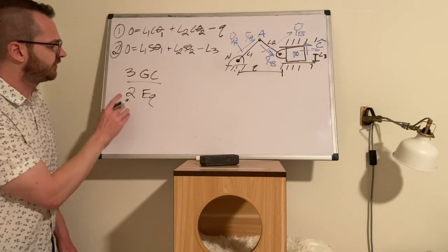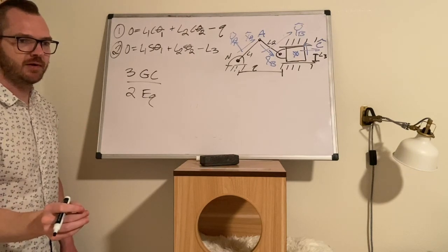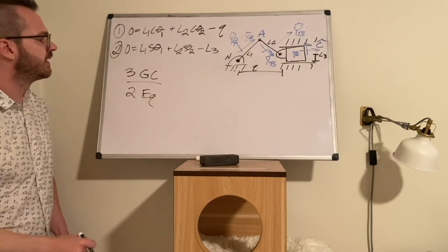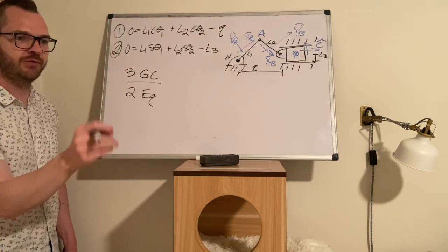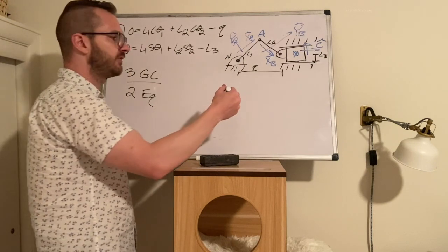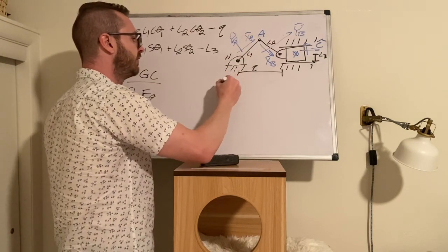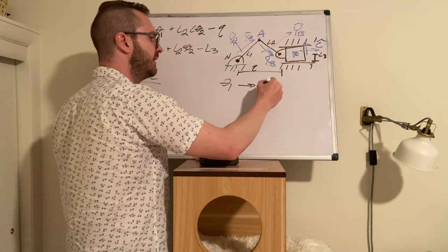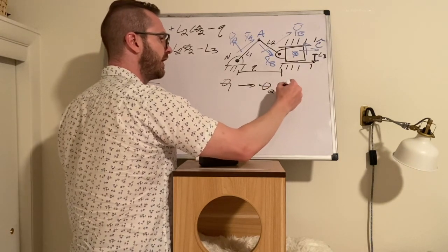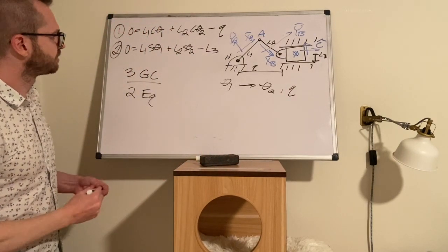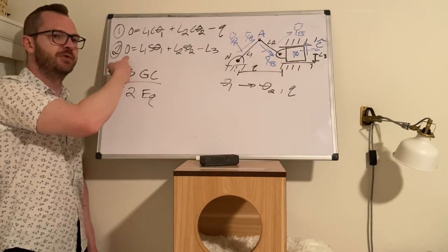That means that your system has an input, and you get to pick that input, or it gets specified through the motion, and then you solve for the other 2 in terms of that input. So we said that this was a crank slider, which means the input is theta 1, and then imagine that you can use theta 1 to then solve for theta 2 and the translation q. Here are the equations to do that.